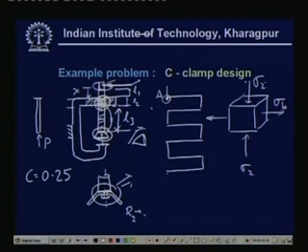Then there will be the shear stress, and shear stress not from the thread pressure, but from the external torque, and that is appearing here. We have the counter shear stress, and this is the state of stress at this point. Similarly, if you want to draw the state of stress, you can do it quite quickly.